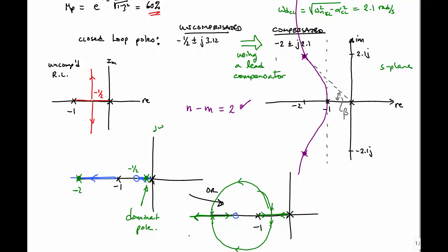And this obviously looks like a little more complicated root locus. But notice that we can achieve closed loop poles, if we wanted to, somewhere out here, right? So in theory, it would appear that we could move the closed loop poles to the left of -1. We could get them to be at -2.